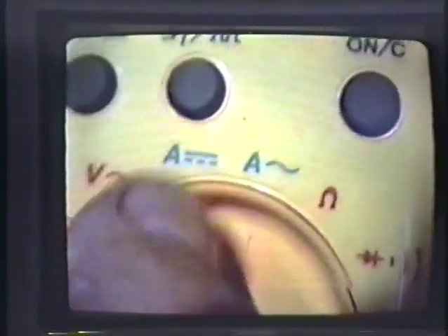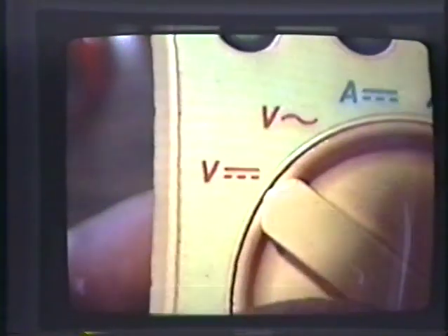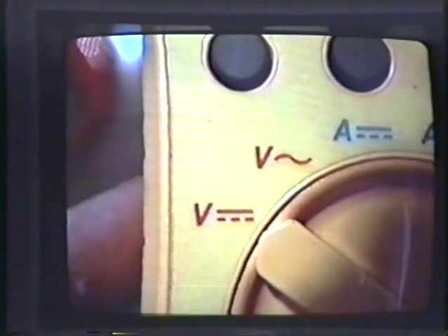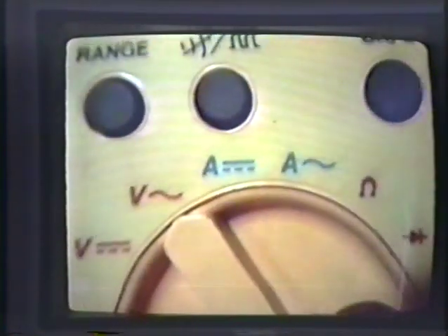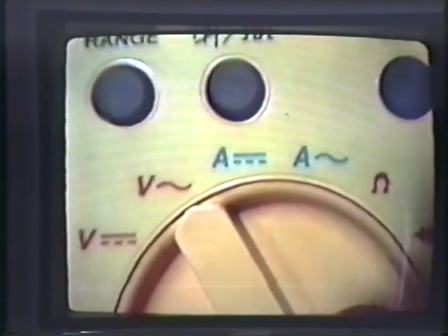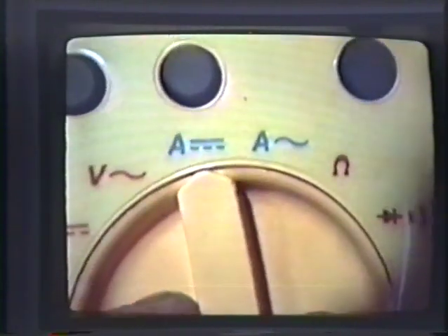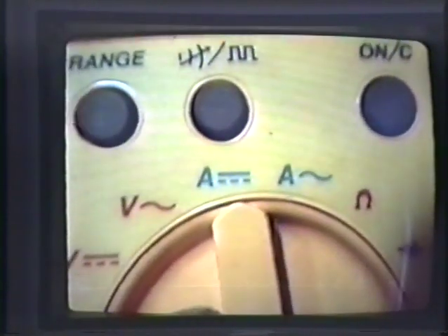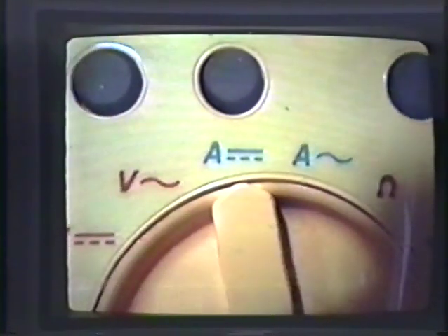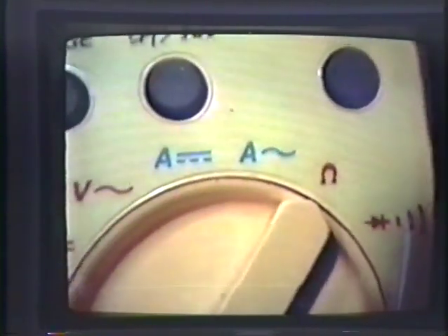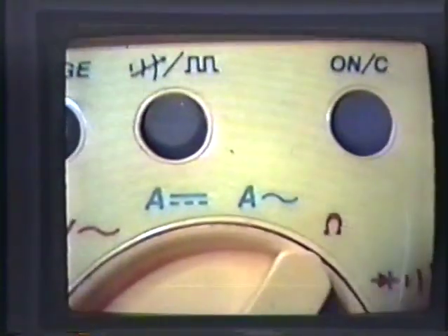So we will measure voltage with our meter. And there's volts. This is called volts DC, volts AC, which we'll talk about the difference in just a minute here. And we will use our meter to measure volts. We will not use the meter to measure current, to measure amps at all. We're never going to use that amp setting, even though it's there, and we could do it, we're not going to ever do it. And then this is where the meter would be set for ohms.